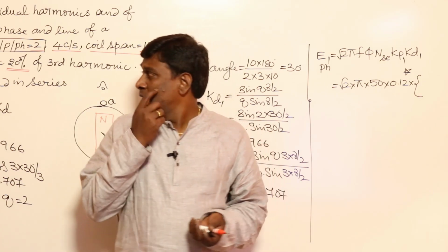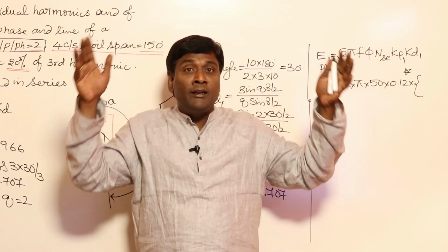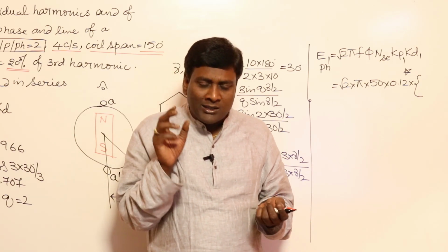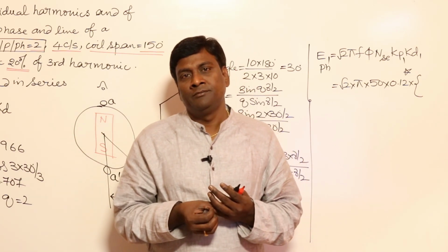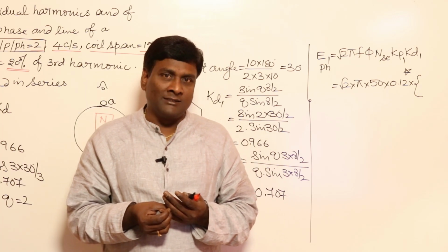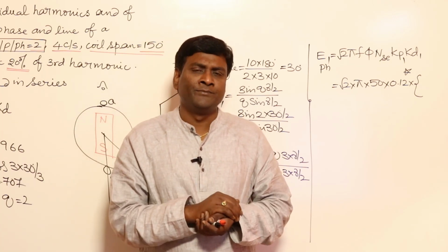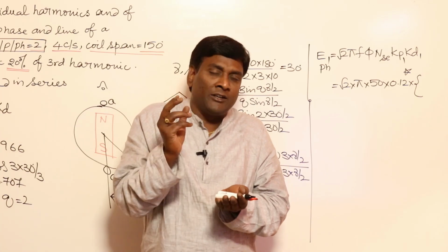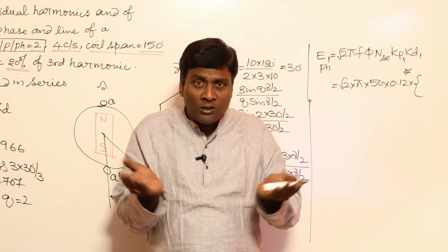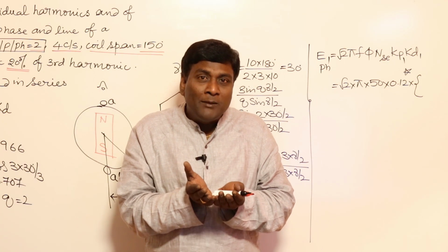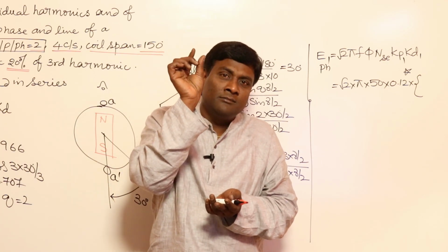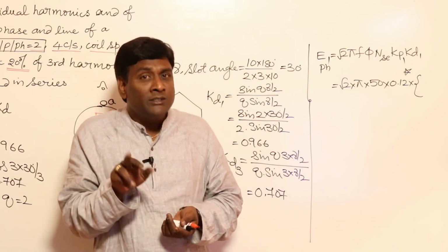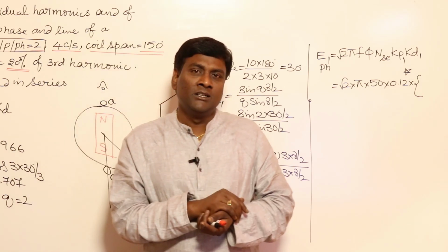Okay, so how many slots are there? Calculate, all of you; we have to feel it. If you try to remember any equation, it may create a lot of problems in your exam because we'll be pressurized in the exam. Okay, see, the total number of slots in the stator, feel it, multiplied by conductors in each slot will give you total conductors, divided by 2 will give you total number of turns, divided by 3 will give you per phase. Though